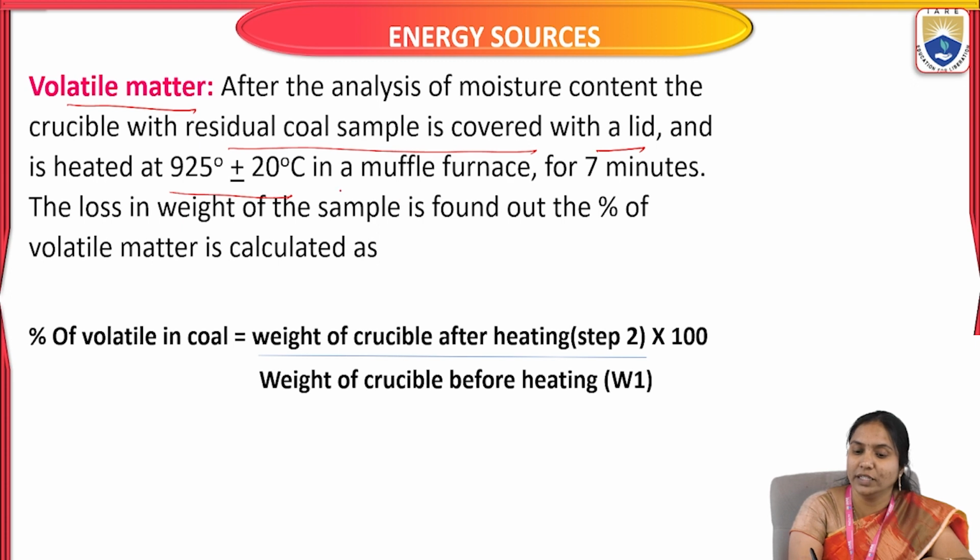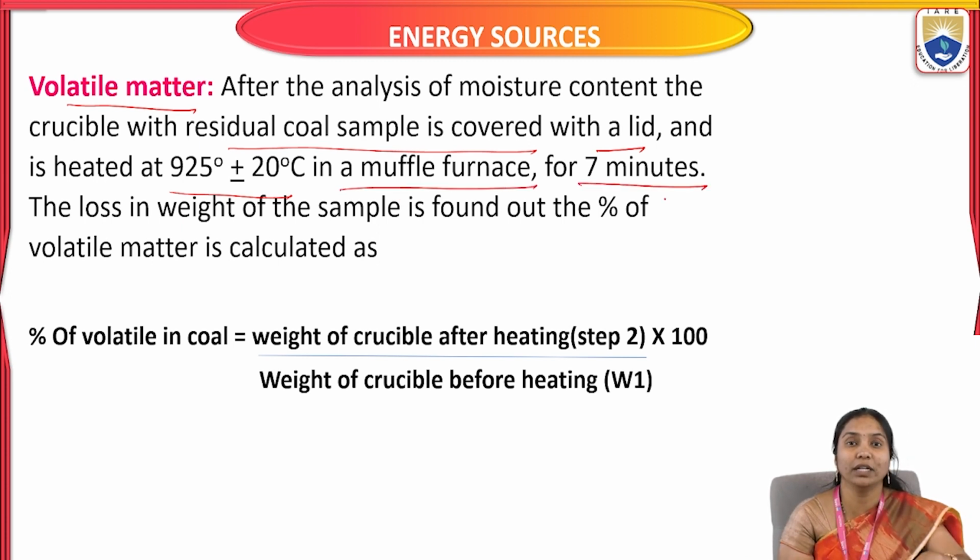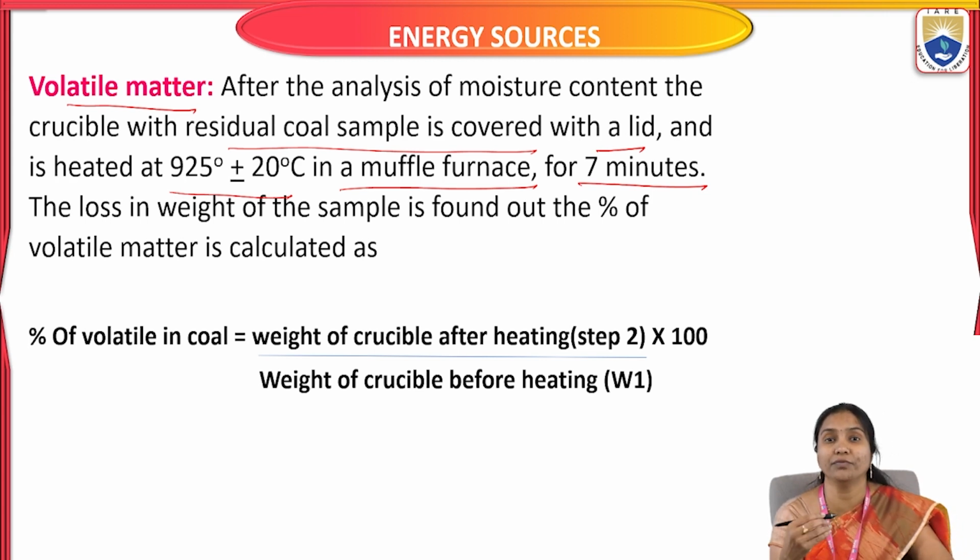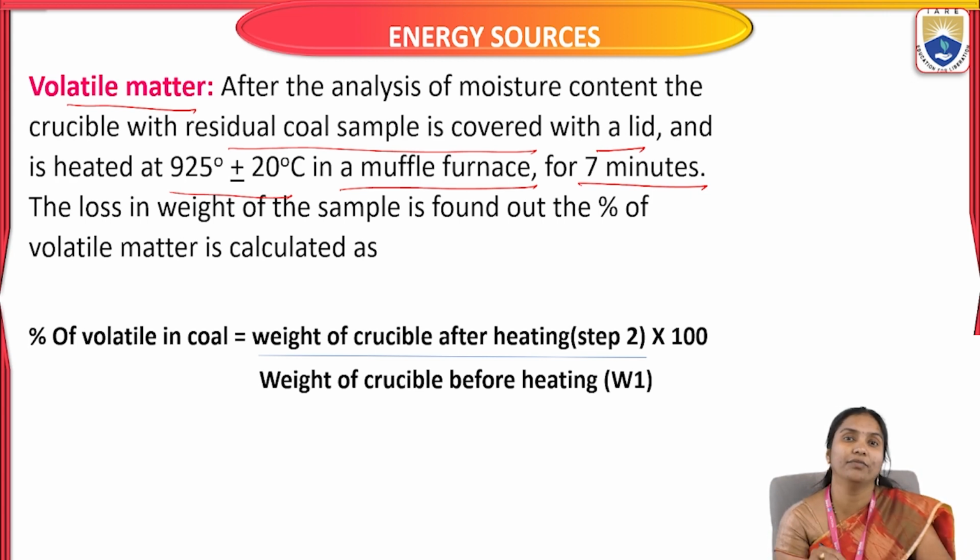And here, it is heated in this muffle furnace. Duration time is 7 minutes. But in moisture content, we are maintaining the temperature at 105 to 110 degrees centigrade for 1 hour.